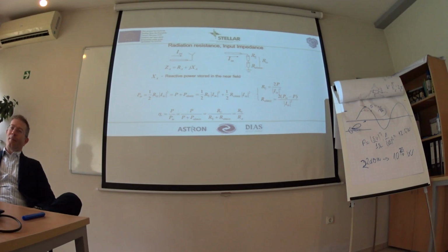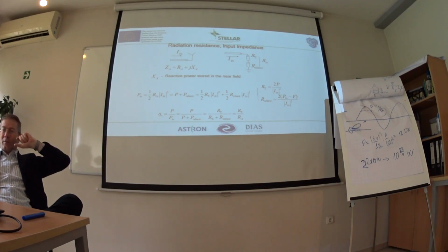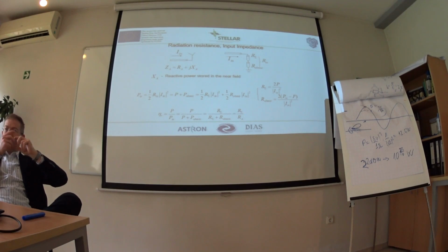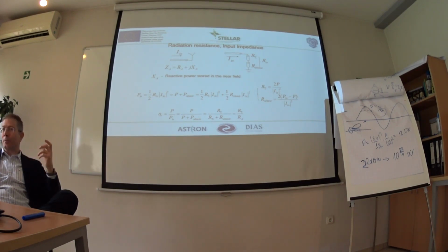So basically, the antenna is either a resonator or a radiator. It's a resonator, and at the moment of resonance, it gives you this impedance. So it's a loosely coupled resonator with the free space. A resonator that consumes energy. And it virtually consumes because it radiates. But from the point of view of the source, it consumes it.